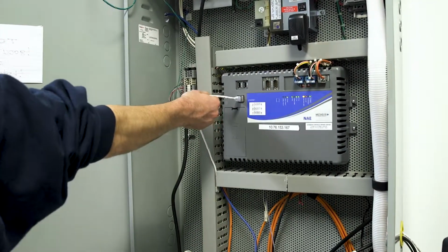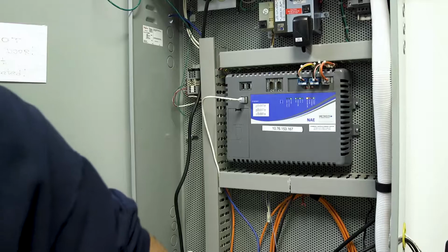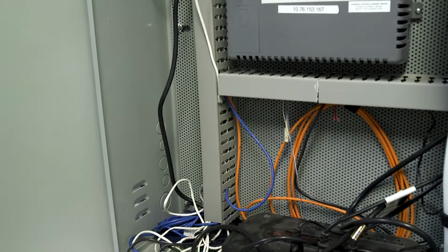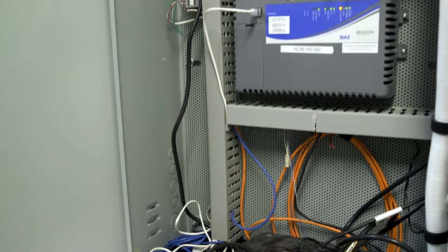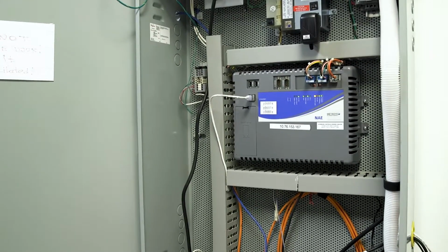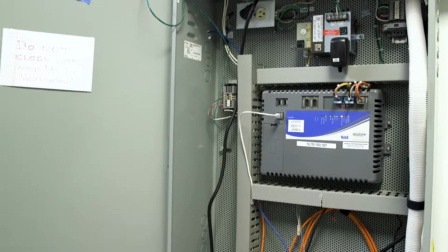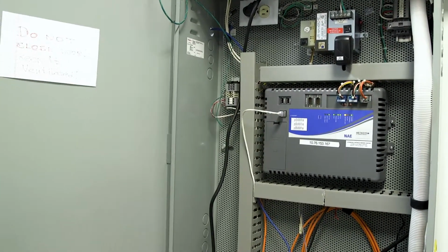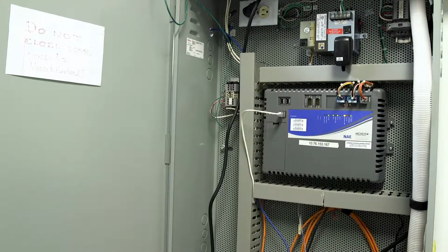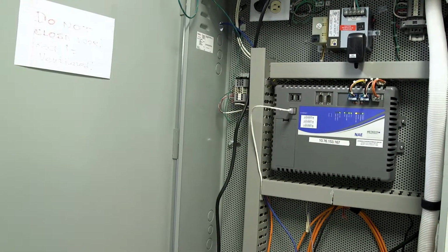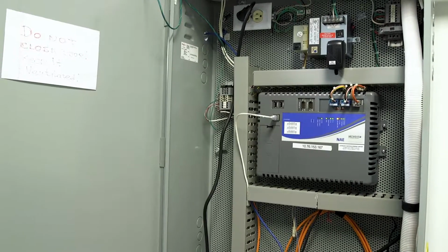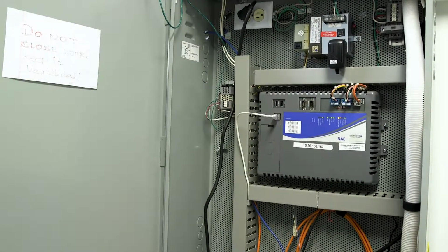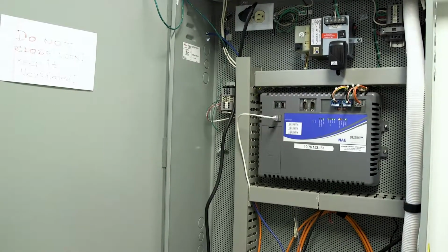Whenever you see a cat cable, it's always going to come back to a network switch, back to the computer. Which is the main one? There is no real main one. There's no boss between them. What they do is on the network, each one has an address. Address 1, address 2, address 3. And it keeps polling through each one. The speed at which they do that is called the baud rate.